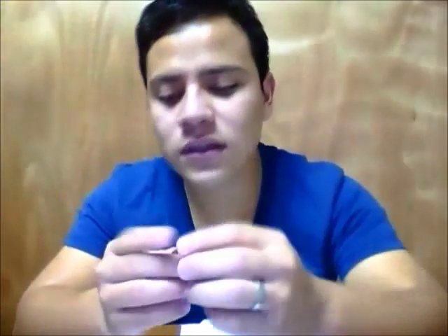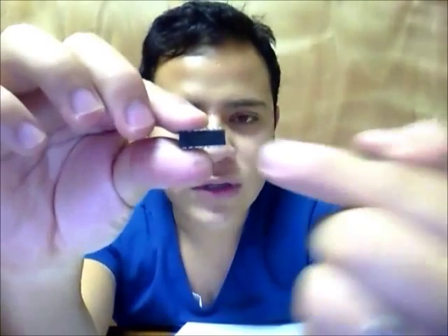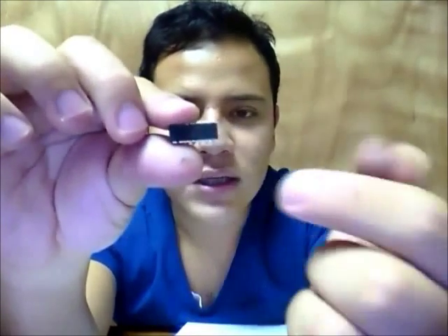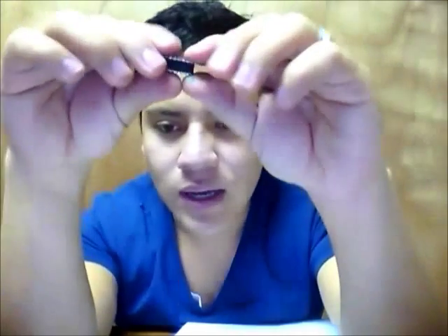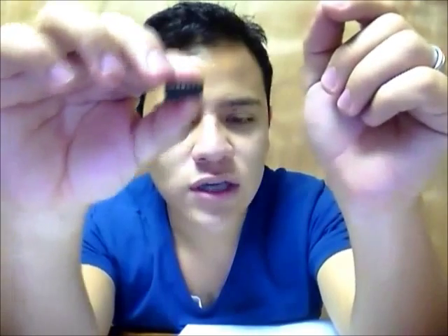The 7432, and I forgot to tell you that we can find the number here. If you want to know what kind of IC we are using, we just need to read the lower part and we can read it. So the 7432 contains 4 independent positive logic OR gates. So we have AND gates, and here we have OR gates.